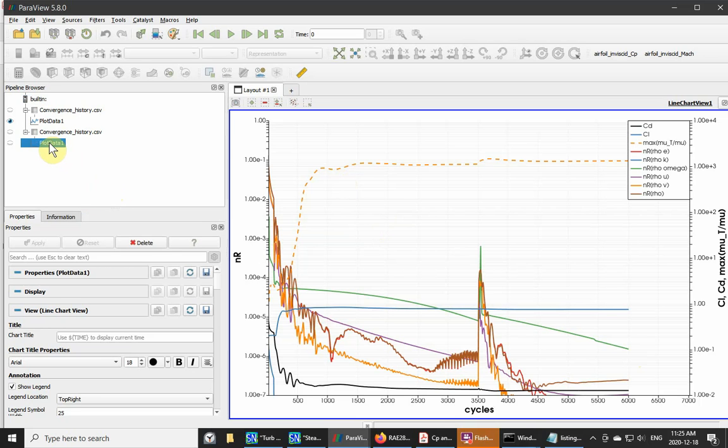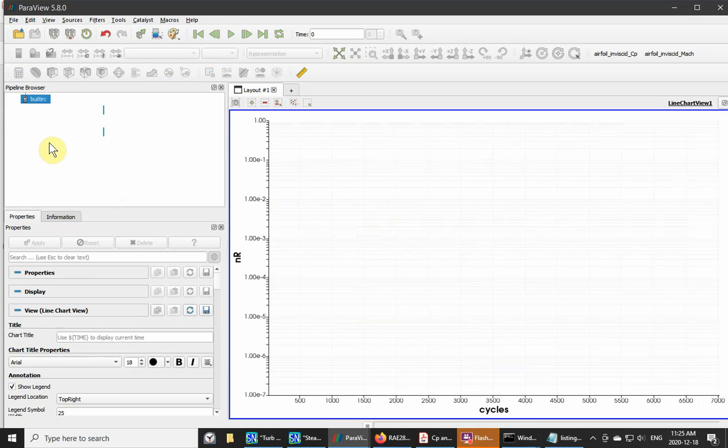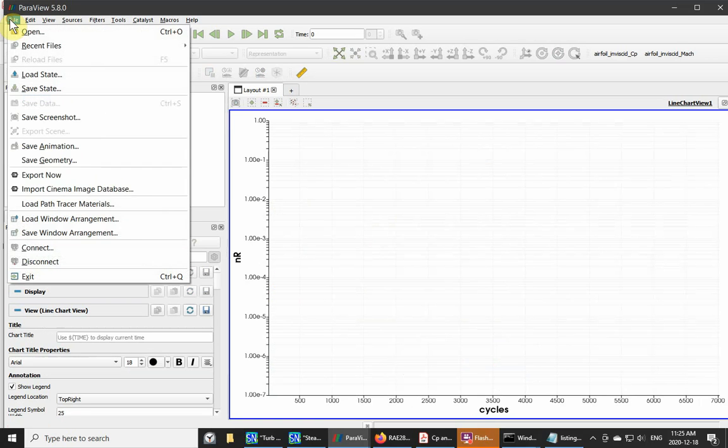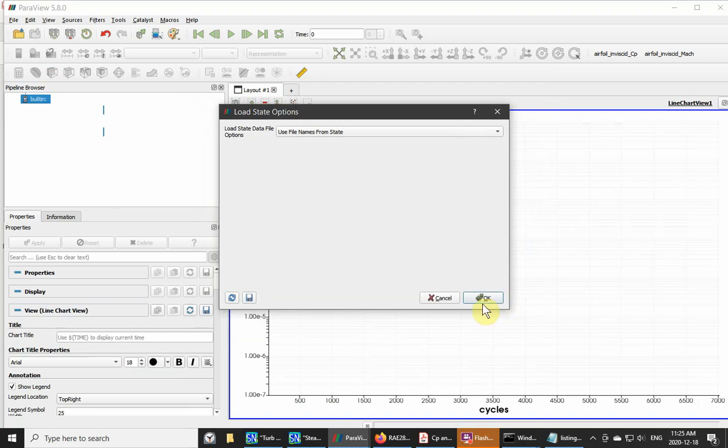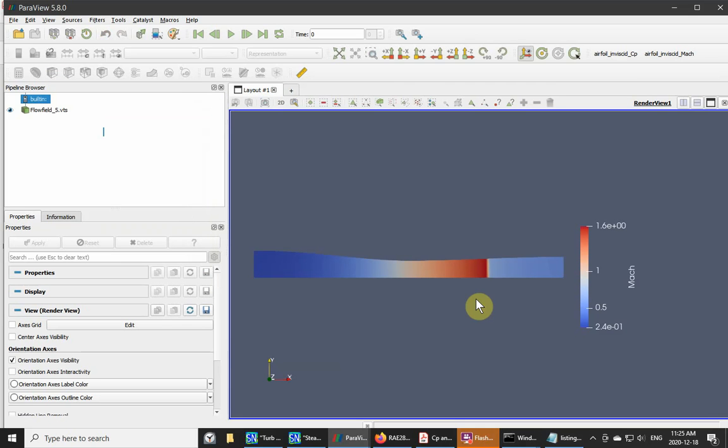And now I'll show you the results for EasyFlow through the nozzle. State. And this first one is for Mach number. And here you have a fairly low Mach number being accelerated till it reaches a sonic value at the throat of the nozzle, and then it reaches Mach 1.6 before it's reduced to a subsonic value because of the presence of the attached shock front.